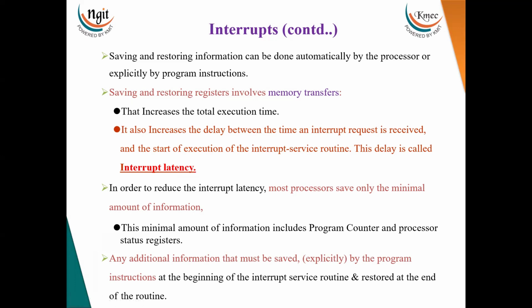It stores the PC value and the status register content onto the stack, and in a few processors it also stores the accumulator and a few important register contents onto the stack. Depending upon how much content it stores onto the stack, the delay takes place. To reduce the delay, in most processors only the PC value and the status register values are stored.